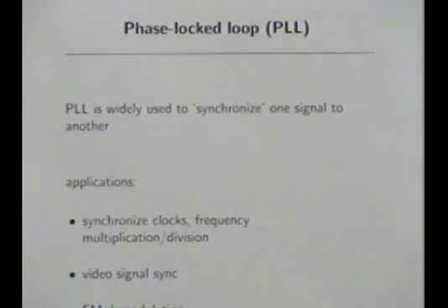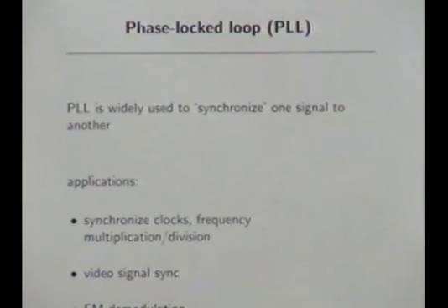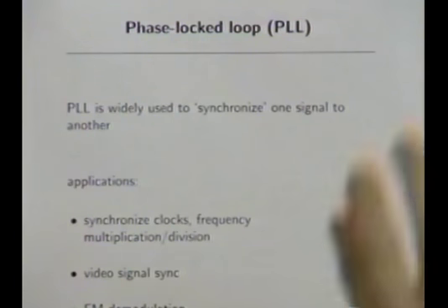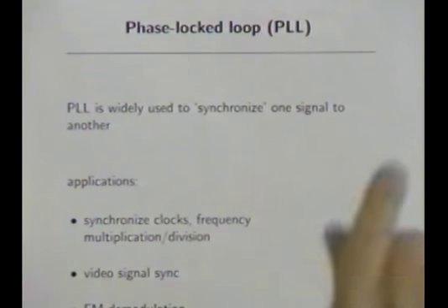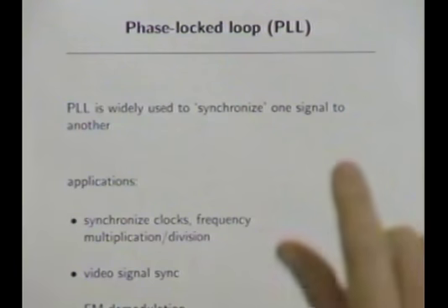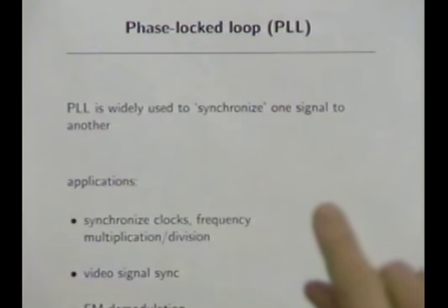Right? So everyone should know about phase lock loops. A phase lock loop is basically a little circuit that takes a signal which is usually approximately sinusoidal, like an FM signal. And what it does then is it has a little oscillator for which it can adjust the frequency. It's a feedback circuit that will adjust the frequency of the oscillator you have there to lock exactly with the incoming frequency. That's the idea. And in fact, it not only matches the frequency, it locks down to the phase.